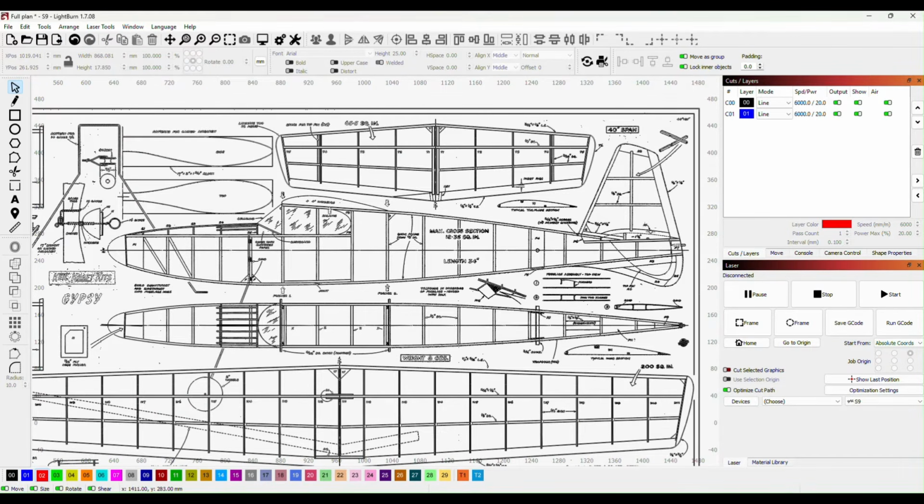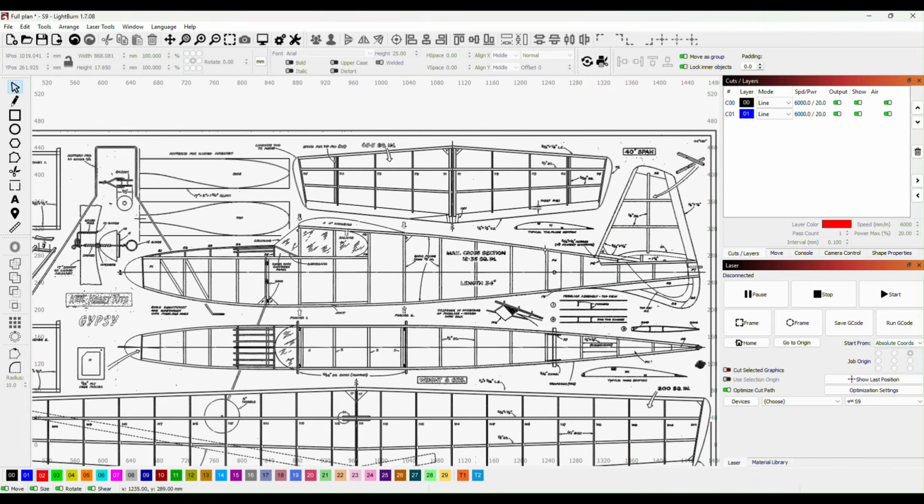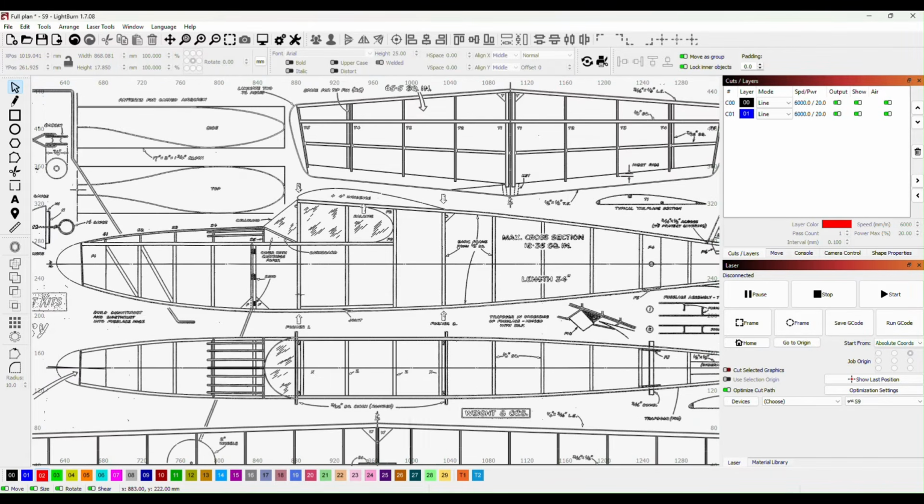Okay, so with the tail fin completed and also this skid at the back, all we've got left to do, when you look at the whole fuselage, which is made up of 1/8 balsa strips, is really this bit around the window and then the nose formers here. But I'm also going to make these two formers here as squares out of 1/8 balsa as well.